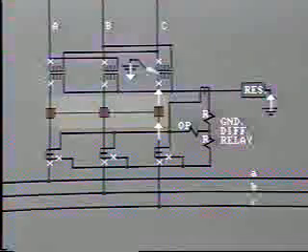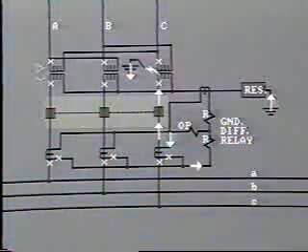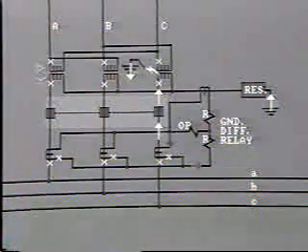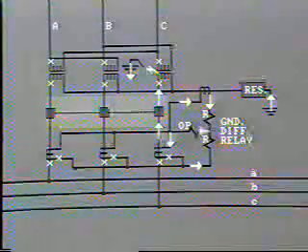But if there is an internal ground fault in one of the transformer windings, the current in that CT will reverse and be added to that from the neutral CT. This current will flow through the differential relay, and it will operate.